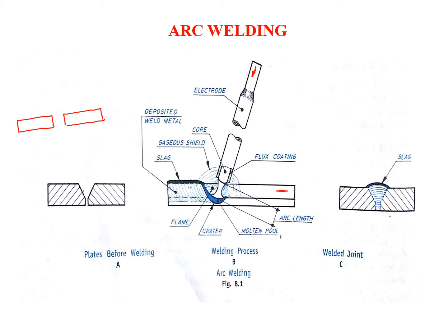joined, and you can see here that it is being chamfered from here like this, and then chamfered from here like this. So this is how we have chamfered it, right? So that the weld material will get deposited here. And then we machine off the upper part, and we get a perfect weld like this, here in figure C.